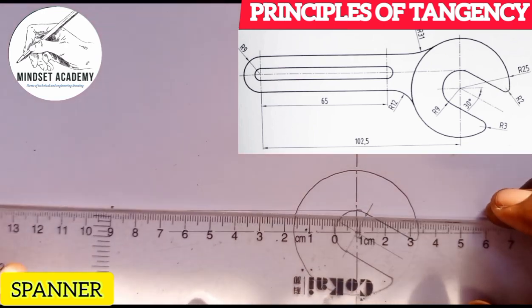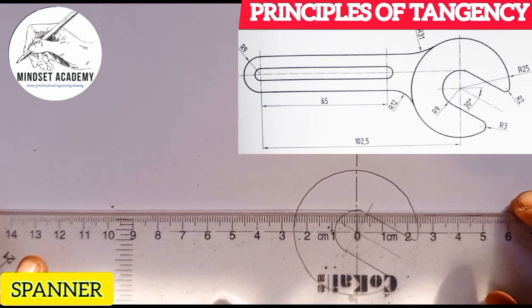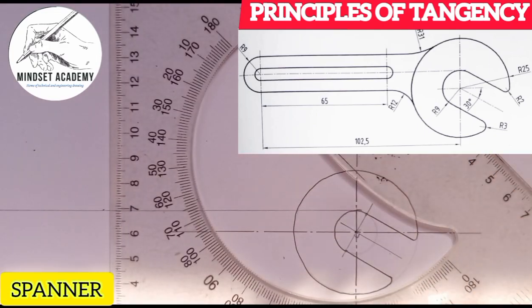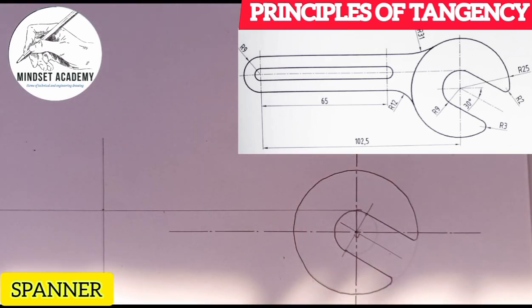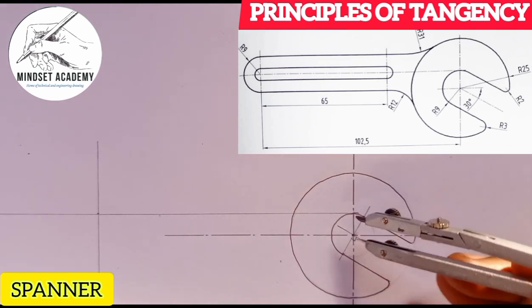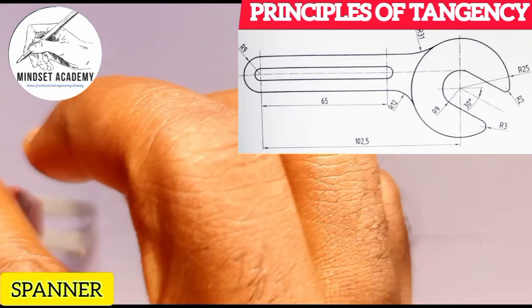If I come here and place it this way, from 0 to 102, this is 102.5 here. And I'll come here and draw my vertical line this way. You can see that. From this point here, there's an arc, a semicircle. It has a radius of 9. So if I place it from here, we know from here to here is 9. I can easily just place it here and draw a semicircle this way.